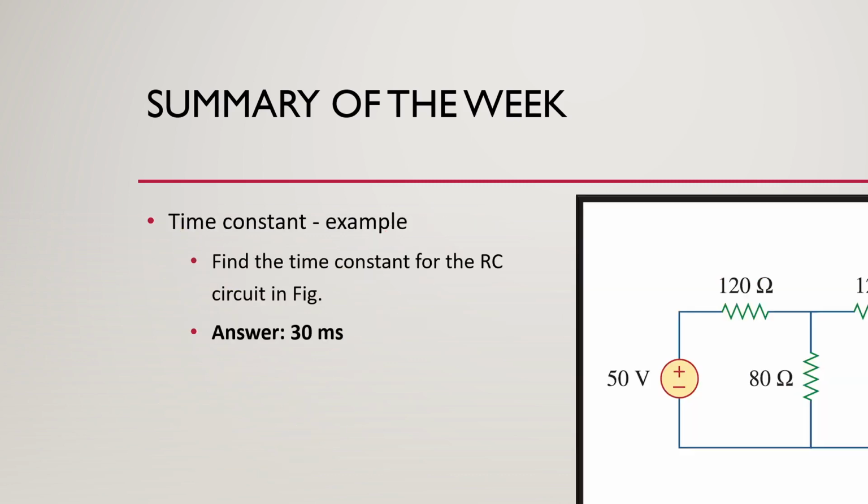So I encourage you, this is a particular circuit, and I have one question. In this case, we have to find the time constant of this particular network. This is an RC circuit, right? You can see that there is a voltage source, but if you ignore this for a moment, you can see that this is only a capacitor connected in some fashion with the resistors. So there are only resistors and only one capacitor, right? So it can be said that it's only a first order circuit.